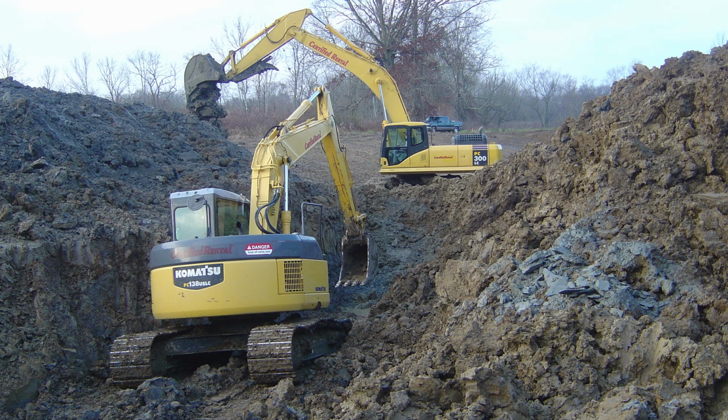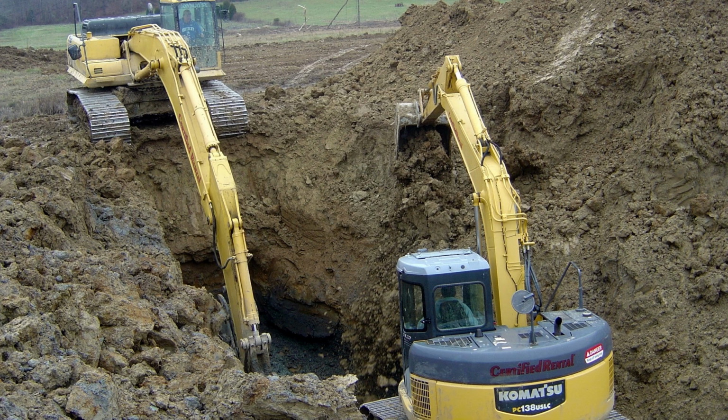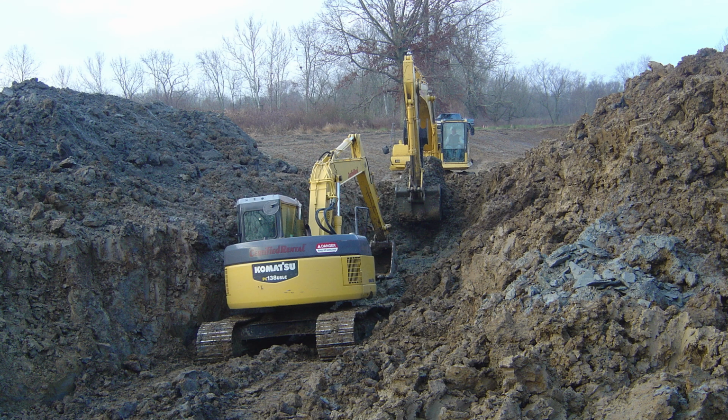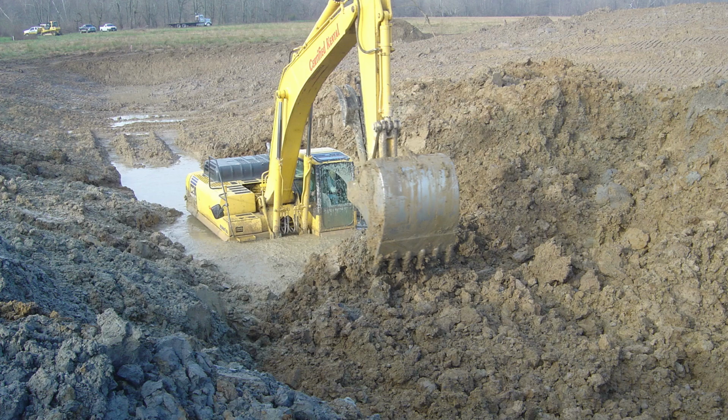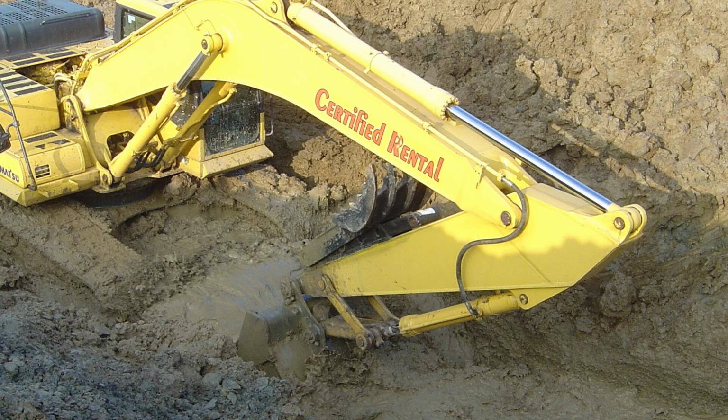The heavy equipment operators worked very well together and they built a high-quality groundwater dam, and they were very careful to avoid collisions. Where the gravel walls in the bottom of the core trench were high and collapsing, the small excavator would fill the core trench as soon as the large excavator had cleaned it down to bedrock. Water would also fill the core trench. The water was removed using the bucket on the excavator so the soil could be placed and compacted.